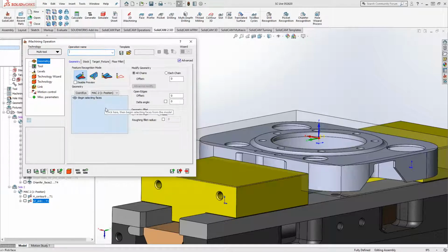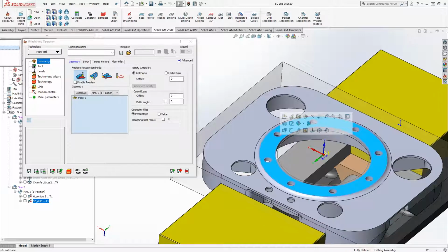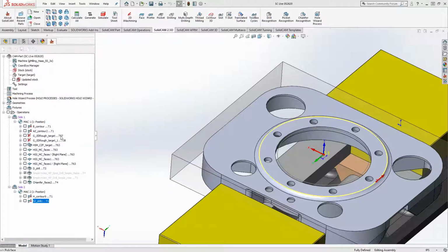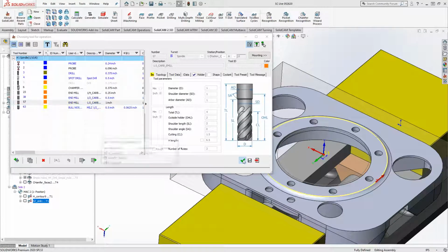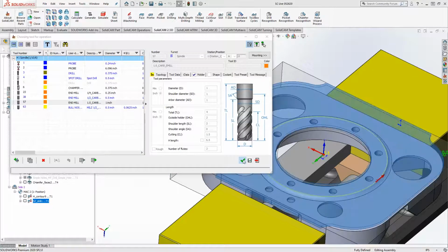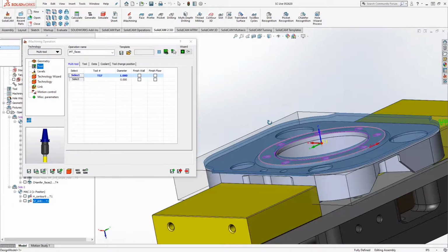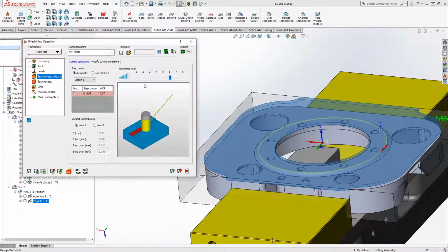So I've opened up 2D machining. I'm going to use that first option. That's letting me just grab a face. And from our updated stock, if I grab that face there, it's just going to extend that outwards and then machine the material. Let's go to Tool. I think originally we used Tool 57. Let's use Tool 57 again. And then it updates the preview to show us we've got that much material to remove if it extends outwards. Perfect. So levels, it read all that for me.